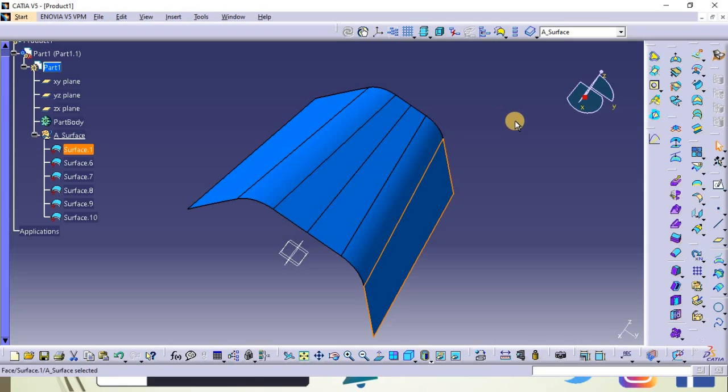To prepare that, numerous operations will be used. The first and foremost operation used is the offset. We have already seen in part 1 of this tutorial what the offset command is. By creating the offset, another surface called the B surface is created. The B surface is the surface which will be behind the visible surface. For example, if you take an insert in the door trim, the surface of that insert visible to the passenger will be the A surface.